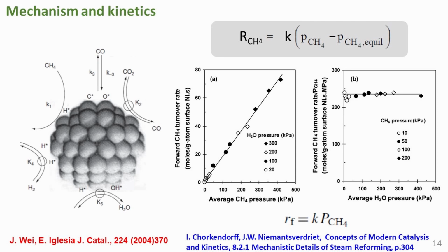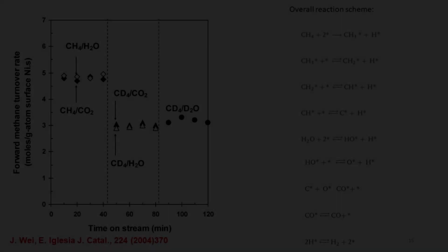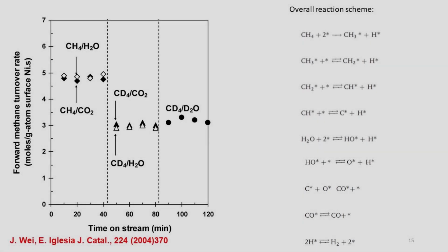rate determining. The work by Iglesia confirmed the first order kinetics with respect to methane, but with no impact on the rate of other reactants. This is in agreement with the general assumption of first order dependence on methane concentration. The work gives strong evidence that activation of methane is a rate determining step. An isotope exchange study on nickel supported catalyst at 600 degrees centigrade with